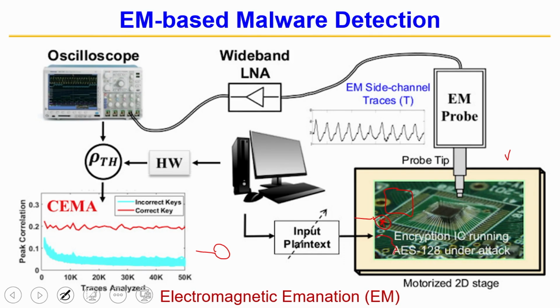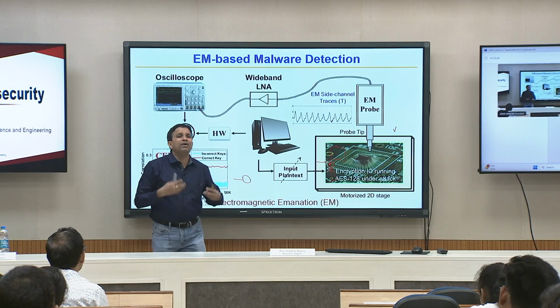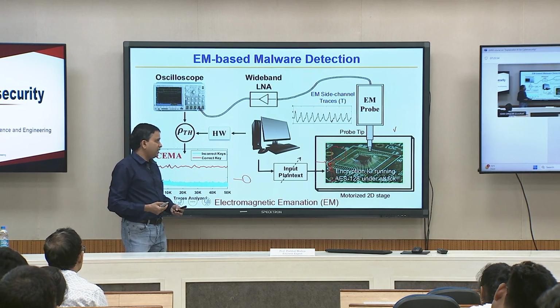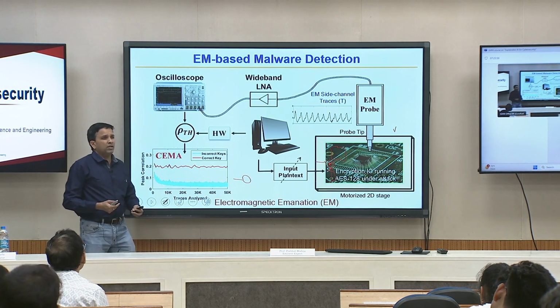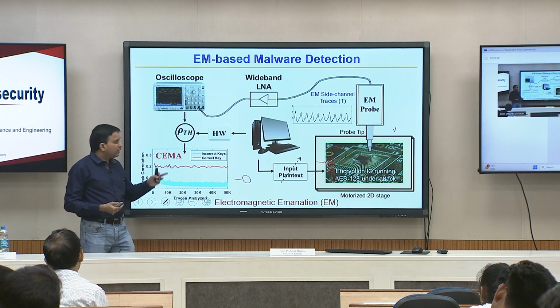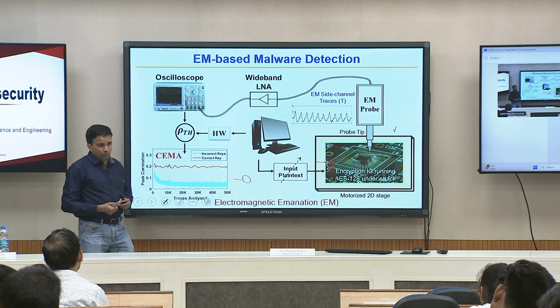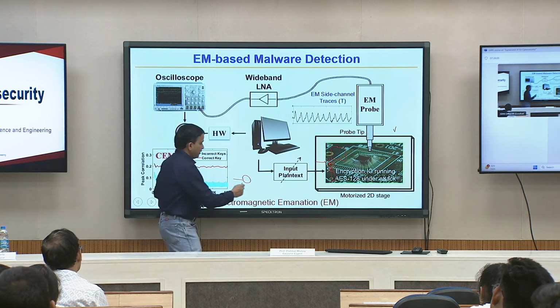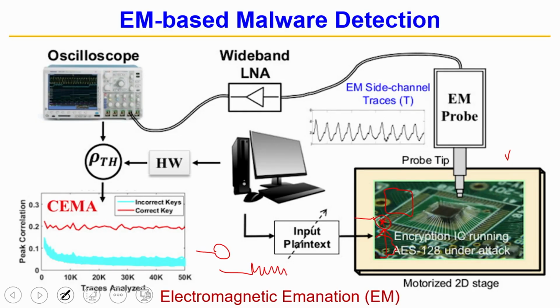Then you have to understand there are other things going on for controlling the FPGA, controlling communication. They will also contribute to this probe, that noise. So that noise is very significant. Unlike power side channel analysis, which is very robust, if I can know how much power you are drawing, electromagnetic emanation is a lot more difficult, because if you do not do it right, what you are going to see is a bunch of noise, even when you are computing, even when not computing.